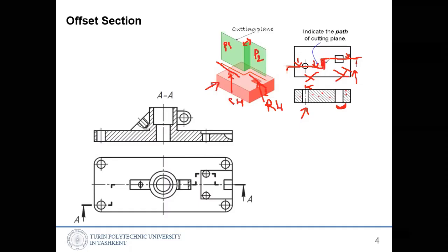And how about here? We are turning to the upper side, so there should not be anything. In some cases students draw a solid line here like this, and that is wrong. There should be no line at all.